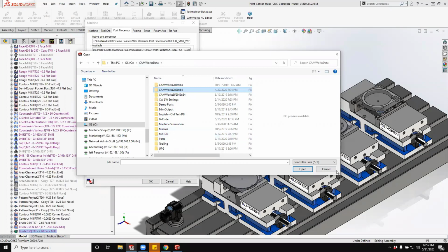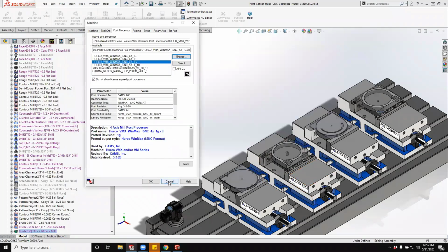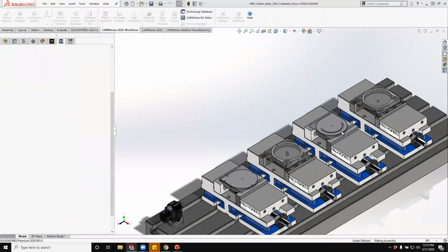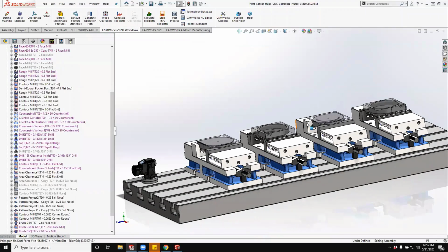We actually had a situation, using some of the standard post logic with one of these assemblies, not this particular assembly, where it was moving from setup to setup and wasn't actually going up to the right heights before it reached the next setup. And we ran into a situation with a tool where it actually knocked into the part.